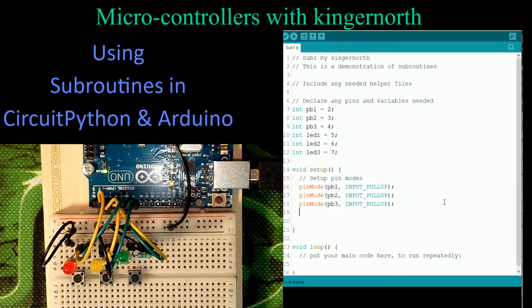The next one I'm going to do is create a new one, and I'm going to call it pin mode, and in this case it's LED 1. And what I'm going to set it for this time is an output. Now, Arduino is kind of funny this way. We don't have to assign everything. I like to assign my inputs and my outputs so that I remember that I've used them. So it's always a good practice. It's not essential. It's just a good practice to go ahead and include all your pin modes for inputs and outputs. So let's copy that.